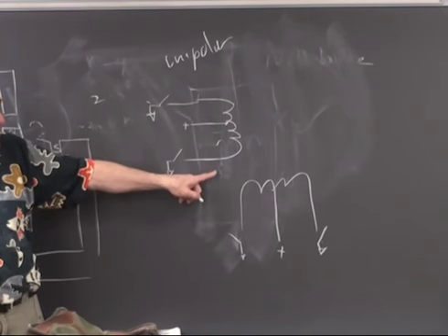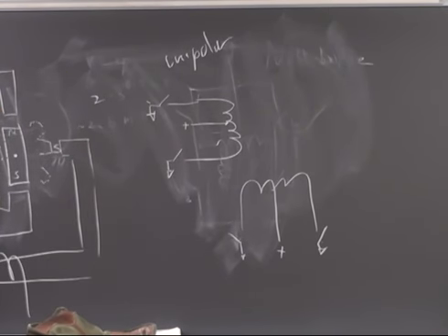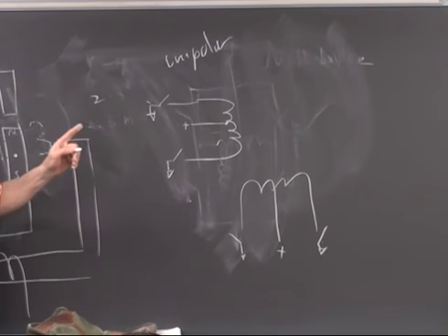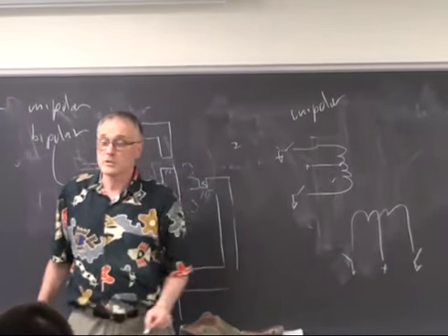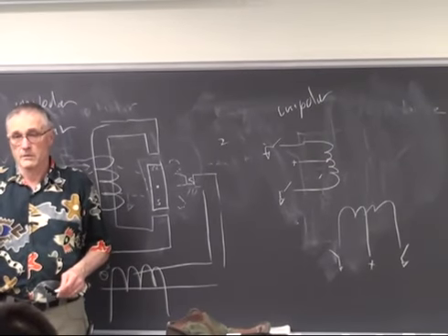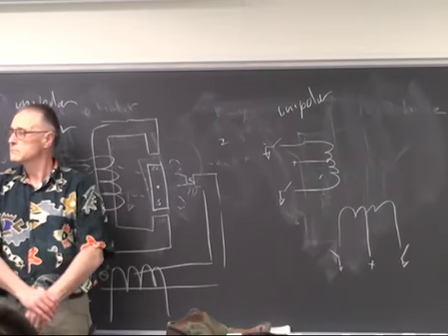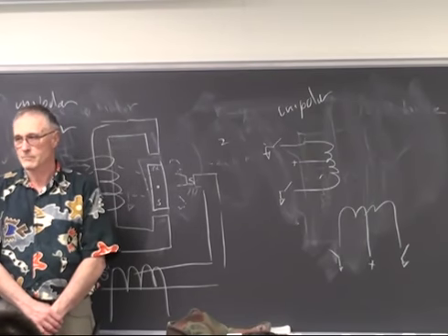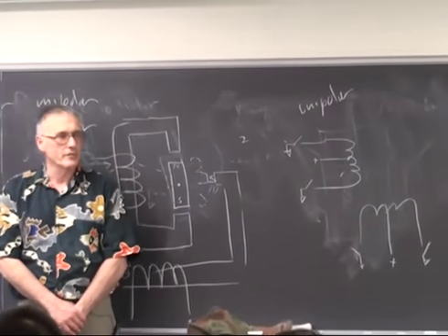If it's 6-wire, you say, well, why would you do this? Well, it turns out the reason for doing it is that it's easier to drive. Because instead of taking 4 transistors per phase, per coil, it only takes 2 transistors per coil. So you reduce the complexity of the external circuitry. That's good. What's bad about this? There's a little difference in the algorithm. It's not so much worse, but it is a little different, yeah.